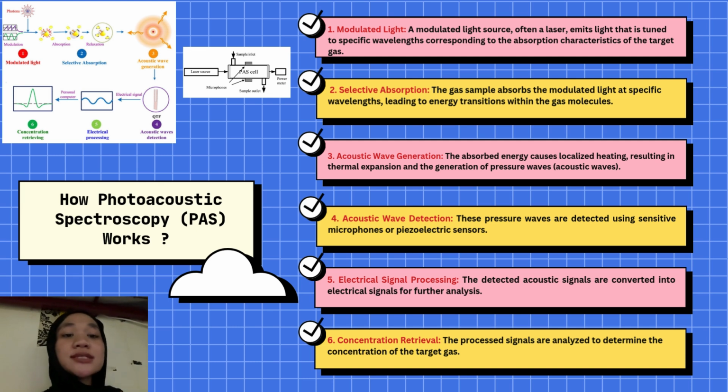The next step is acoustic wave generation. The absorbed energy causes the gas molecules to expand and contract as they heat up. This rapid heating results in the generation of pressure waves, also known as acoustic waves. Essentially, the light-induced energy causes the gas to behave like a small engine that creates a sound wave. Next, these pressure waves are detected by a very sensitive microphone,